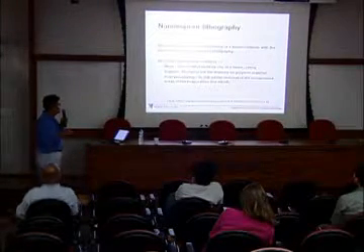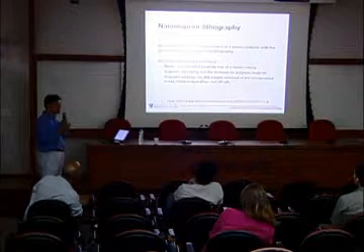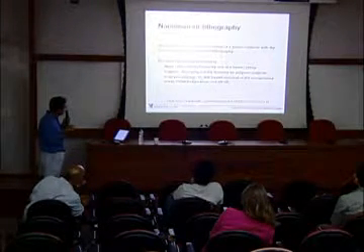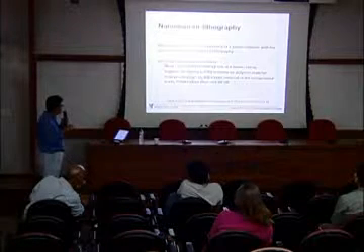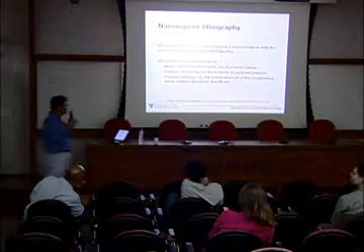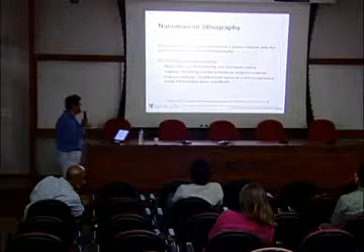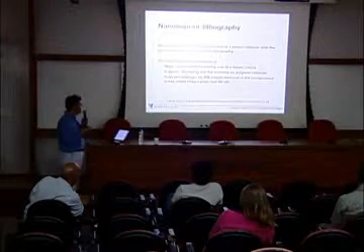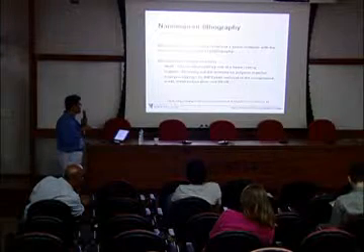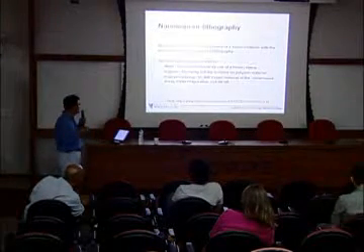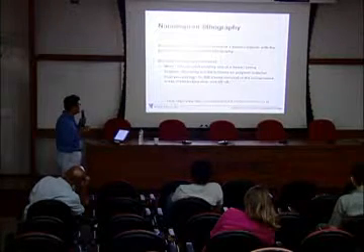Then we have a stamp, but at this time it's a hard stamp. It's not a soft stamp. And then imprinting is happening. We can use a mold, and the mold will be placed on a polymer layer, and then with heat and pressure, the polymer can be patterned. And post-processing is to clean up the surface with oxygen. Some of the polymer will not be transported on the surface. Those debris will be removed using these post-processing steps.